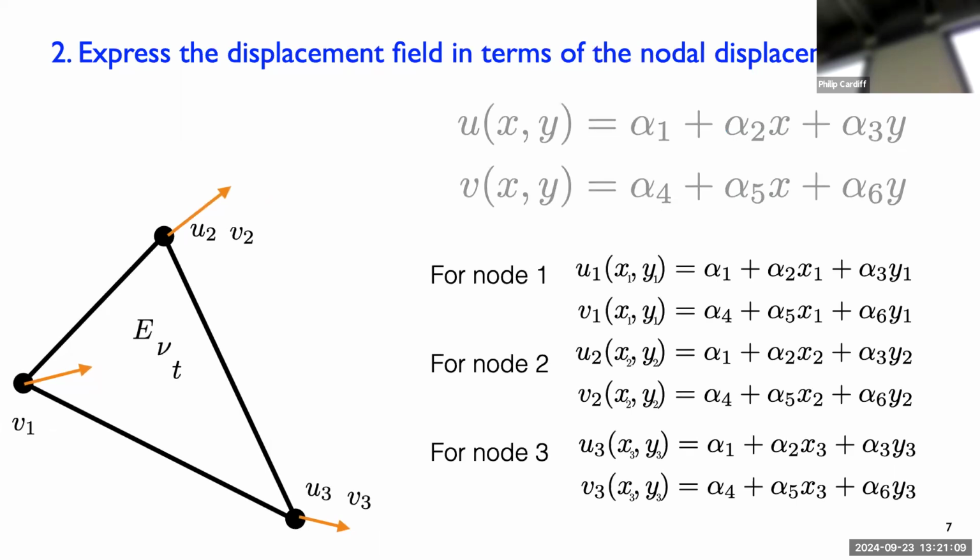If this is a first order polynomial, these are called linear shape functions or linear interpolation functions. These are the default in Abaqus. But we could use quadratic ones. So we could, with extra constants, have an X squared, a Y squared, and actually an XY term as well. So 3 extra for each one. And that would give us quadratic functional forms or quadratic shape functions. In Abaqus, you go to the element controls, and you can tick on quadratic if you want it as well. You'll say, well, how can I calculate the constants if I have quadratic?